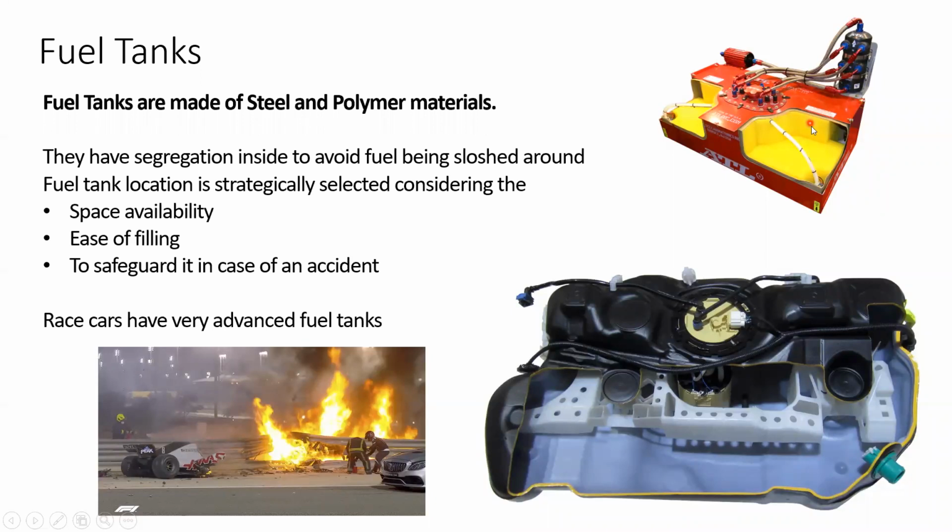You can see inside of that it has foam inside the fuel tank. In normal vehicles, we don't have this foam. The reason for having this foam is that once we fill the fuel, it will absorb the fuel into the foam. It will absorb and expand, right? Even if the vehicle was turned upside down, right?